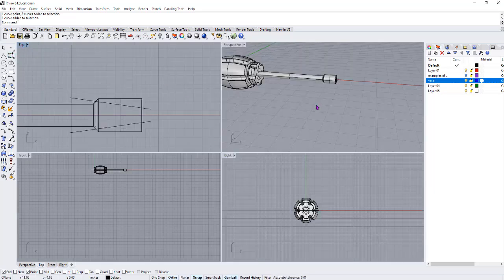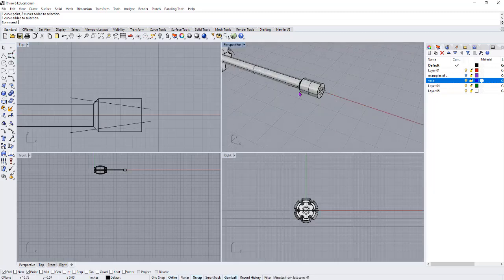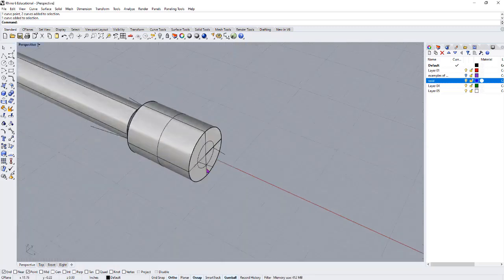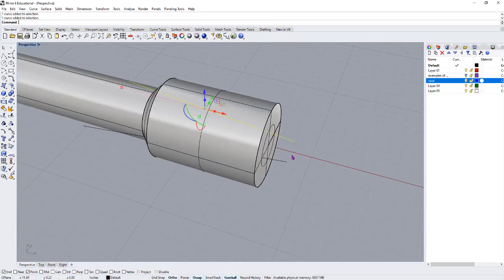And now I'm going to go in my perspective. If I can run it in my top elevation, either one, it will be fine. And then I'm gonna say those will be my cutting objects, but it needs to be one P line, so I need to connect those two. Join, and I'll say wire cut. So the cutting object will be this P line, enter.